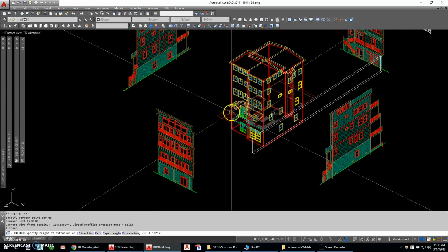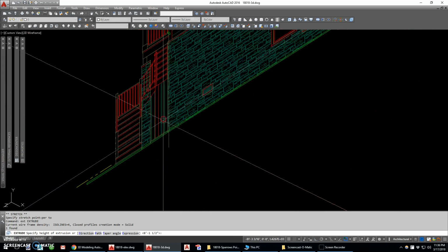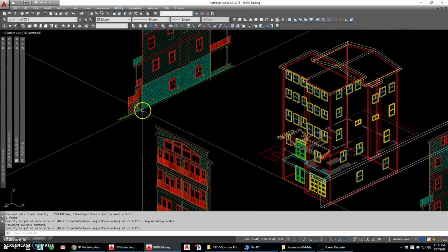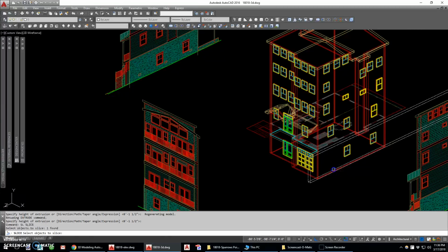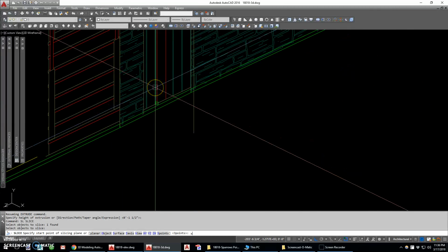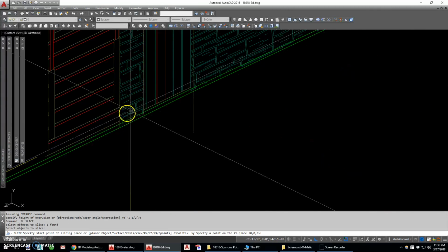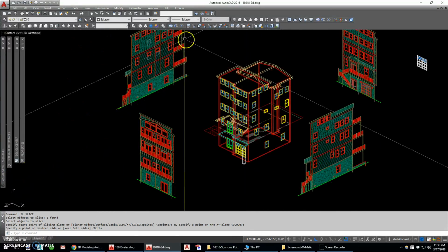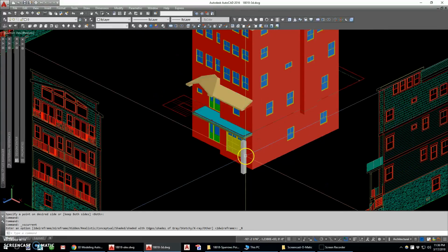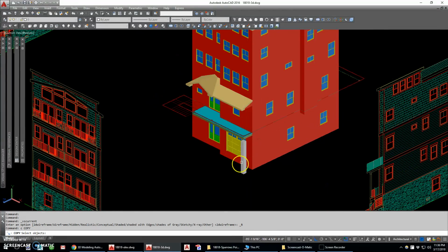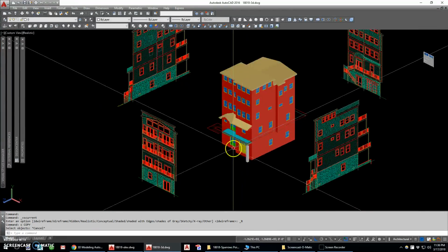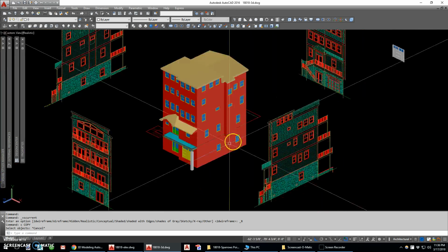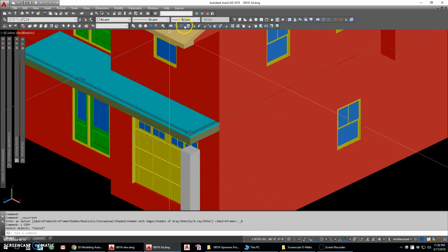I'm going to extrude that out. I'm going to go look at this elevation and extrude it out to the edge of the column. Slice it on my XY plane and just keep the front. Now I've basically got my stone column there. Before I copy that to make the other two, because I'm sure they're identical, I'm going to go ahead and put this cap on top.